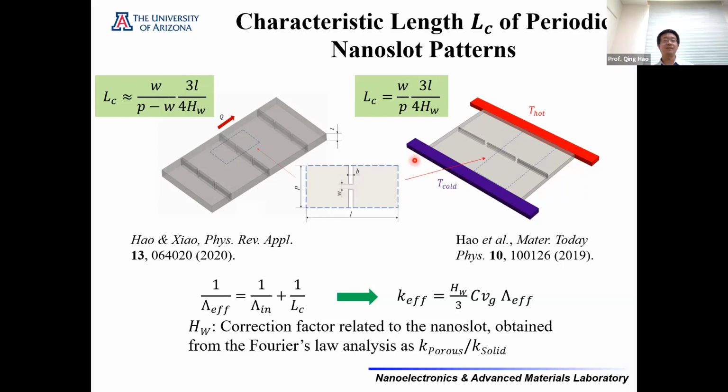The state-of-the-art fabrication for the EBL, electron beam lithography, you can define sub 10 nanometer pattern, right? But you can define that pattern doesn't mean you can fabricate those small holes across the silicon thin film, because usually there is an aspect ratio restriction for dry etching, right? When you etch a hole, the ratio of the diameter and the depth of the hole, you cannot have very high aspect ratio for the hole. Usually it's 3. So if you got the thickness of the film like 70 nanometers, the smallest pore size will be 20 or something nanometer, right?